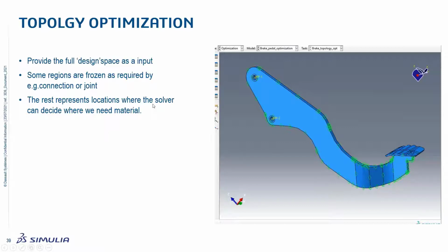This is known as an optimization process, and obviously an optimization process is done with certain objectives. And most of the time, topology optimization is done with an objective of reducing the mass. So basically, we are starting with the full mass of the design volume, and we can set a target for how much we want the mass to be reduced from this state.